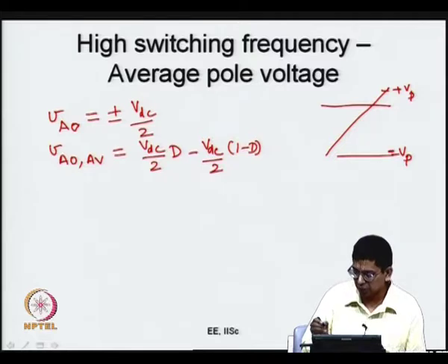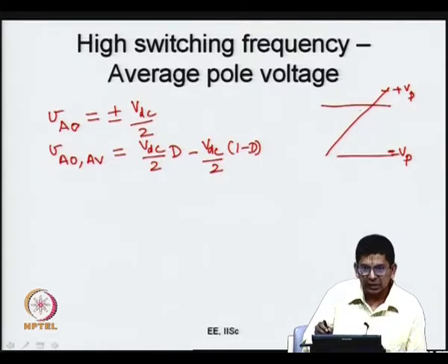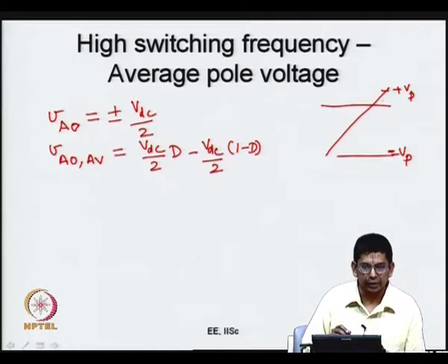So, what do we do when we are switching? Whenever the modulating signal is greater than the carrier. Now, I have regarded the modulating signal as a DC, because we are looking at a very short interval of time. It is much shorter compared to the fundamental cycle, and therefore you can ignore whatever variation you have in the sinusoid, or you can take it as the sampled value of the sine. So, it is a flat line here.